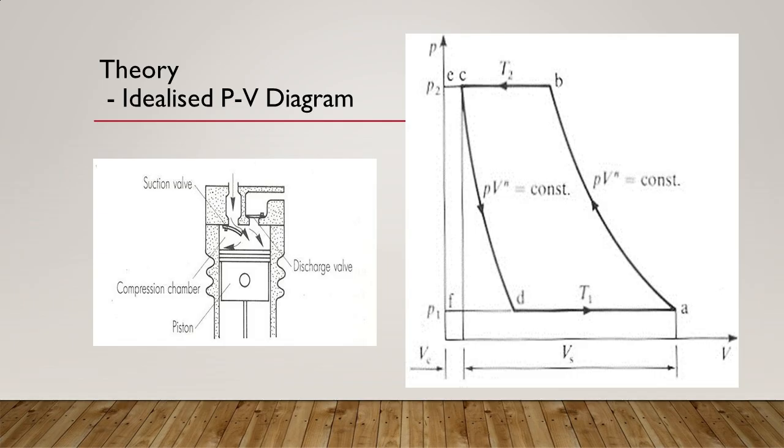This PV diagram is an idealized cycle of the reciprocating refrigerant compressor. When the delivery stroke BC is completed, the clearance volume VC is full of gas at pressure P2 and temperature T2. As the piston proceeds on the next induction stroke, the air expands behind it, until the pressure P1 is reached. Ideally, as soon as the pressure reaches P1, the induction of fresh gas will begin and continue to the end of this stroke at A.